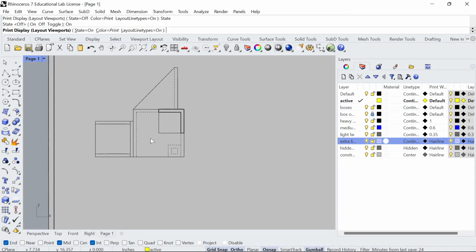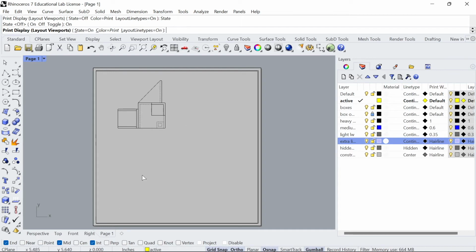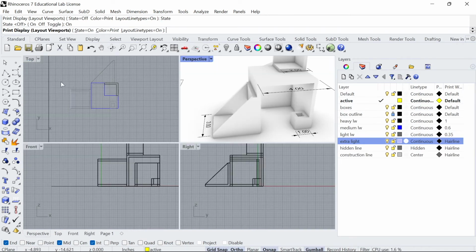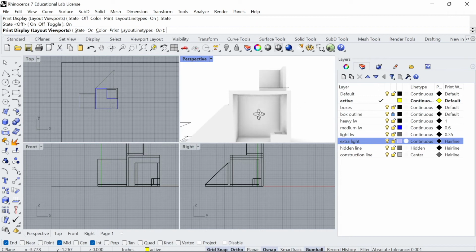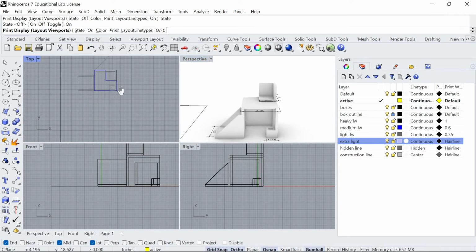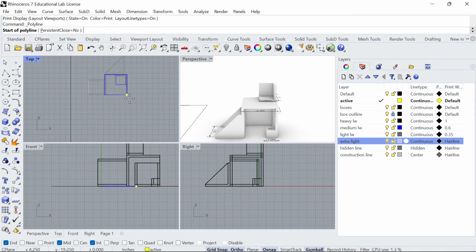Okay, so the next thing you want to do is create the next 2 side views. So the next one I'm going to use or draw is the one right below it, which will be a side view, kind of as if we're looking at the object from this view. The way I want to approach this is kind of similar. I'm still going to need to use the measurements and understand what's going on. Now, you may want to kind of draw these construction lines to get us to a certain direction. I'll actually draw it like this.